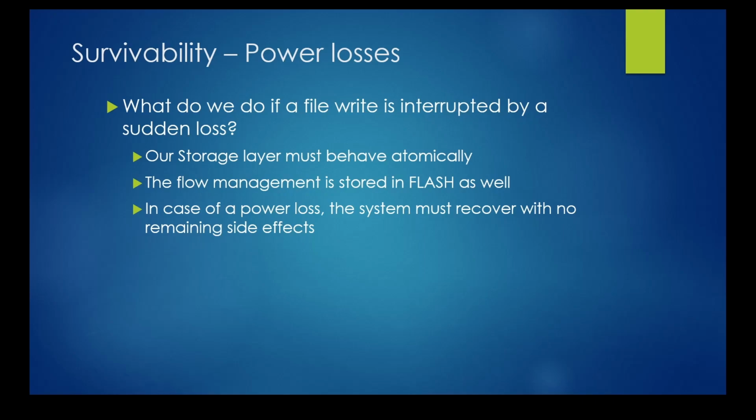How? By bookkeeping every step in the file write process. The bookkeeping data itself is saved on non-volatile memory so we can read it during boot in case the system went down due to a power loss. If we have recorded the file write step this way, on our way up from the power loss, we can also know if we went all the way through with the file write or if we were cut somewhere in the middle. In that case, we can do cleanup operations to remove side effects. So yes, the file will behave as if it was never written, but at least we will not consume corrupted data.